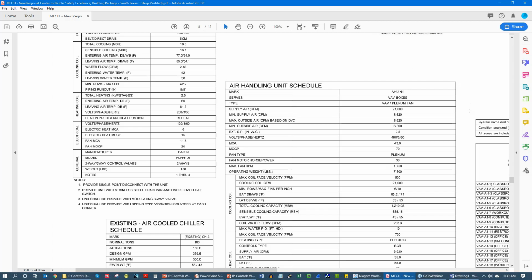Those are things where, if that particular device fails, it's not the end of the world. But if that controller fails and all of a sudden you lose the air handler, that's a much bigger deal. So hopefully that made sense, my reasoning for why I would not recommend starring off of a ring or a bus for these types of equipment.